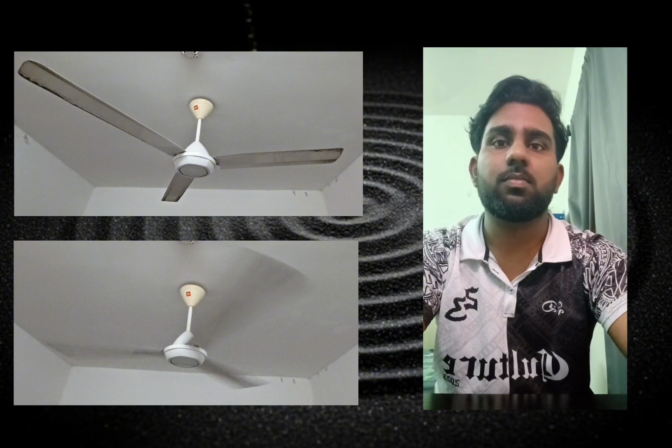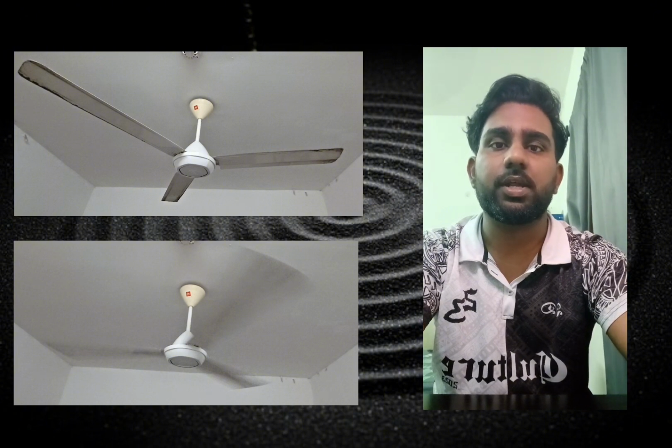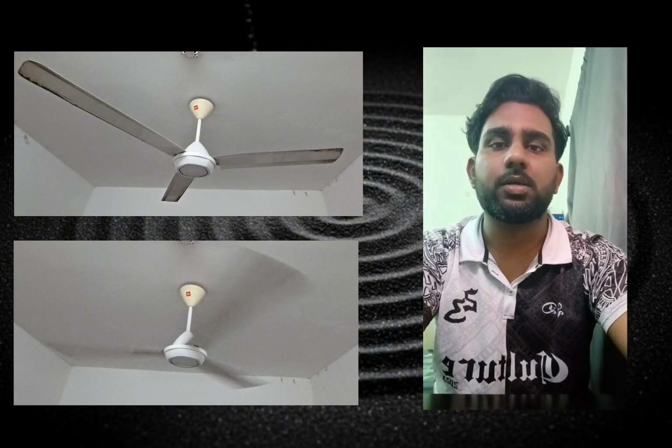I measured the central motor hub radius as 0.11 meters and the length of each of the three blades as 0.55 meters. By treating the hub as a solid cylinder and applying the parallel axis theorem to model the blades as slender rods rotating about a fixed endpoint, I calculated the total mass moment of inertia about the fixed rotation axis, I0, to be 0.378 kg·m².